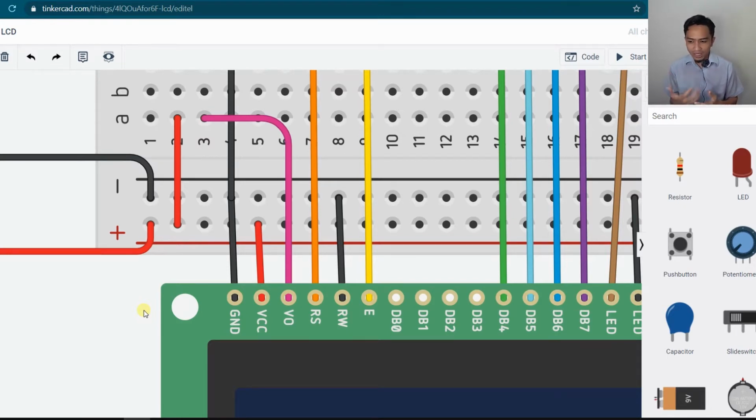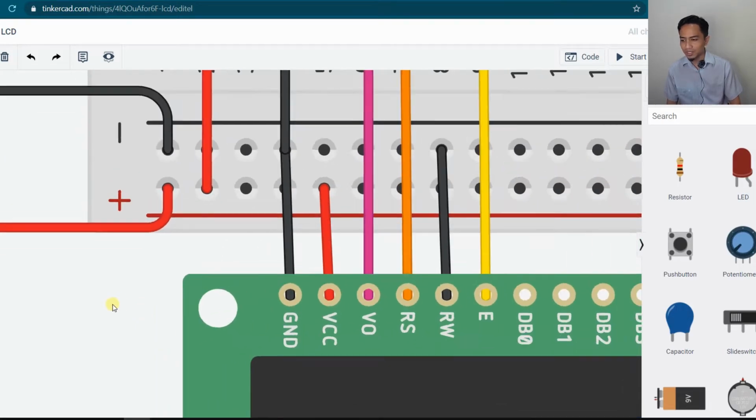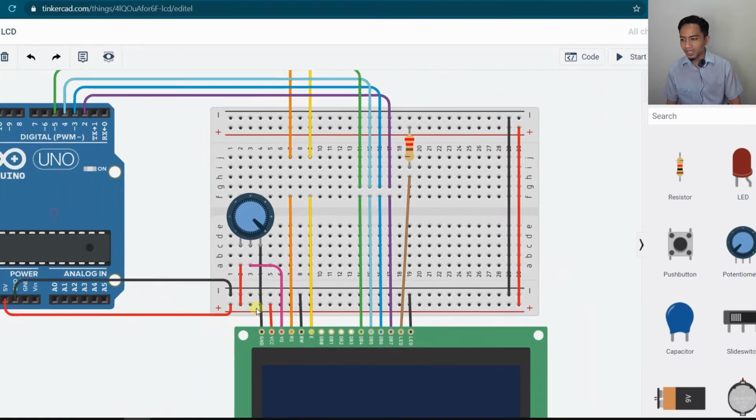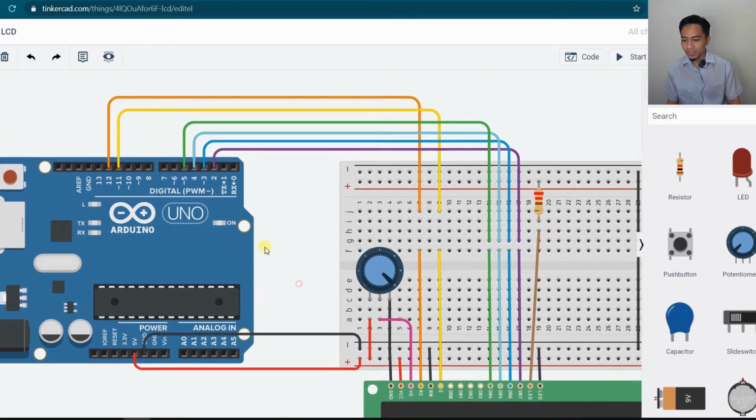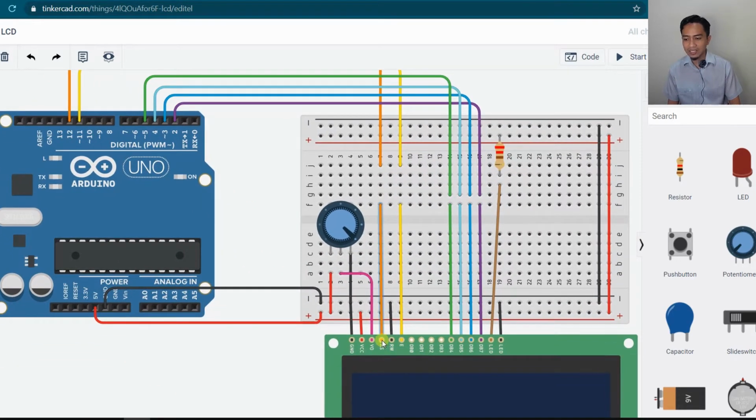And for data, it will set high, which means if you just want to display data to the LCD, it sets pin 12 to high. So this is how the RS port is functioning.